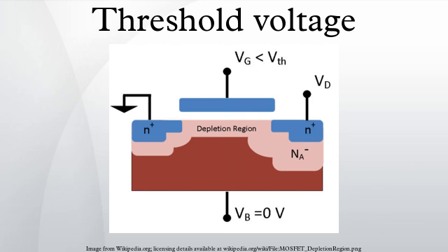Where VTN is the threshold voltage when substrate bias is present, VSB is the source-to-body substrate bias, 2φF is the surface potential, and VT0 is the threshold voltage for zero substrate bias, γ is the body effect parameter, tox is the oxide thickness, εox is the oxide permittivity, εsi is the permittivity of silicon, NA is the doping concentration, and q is the charge of an electron.